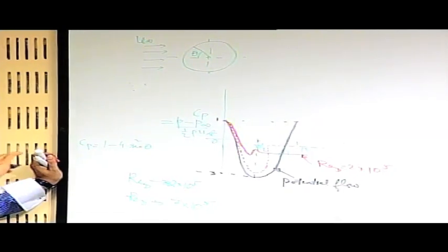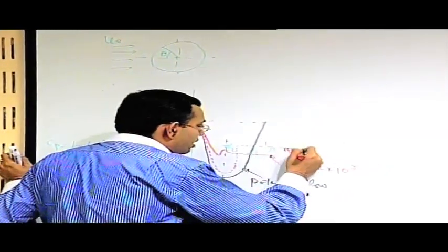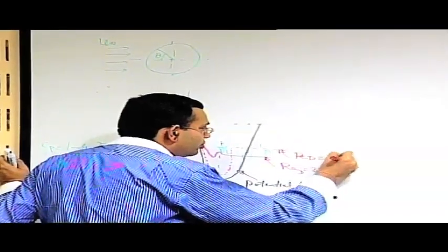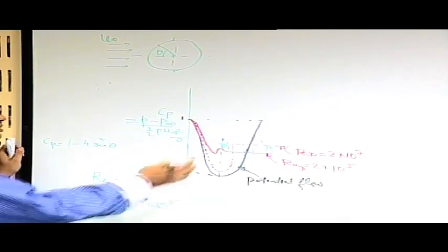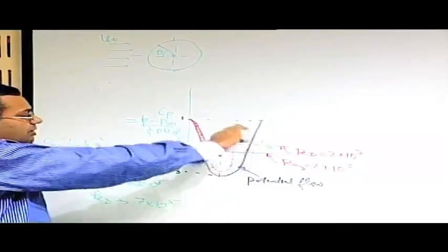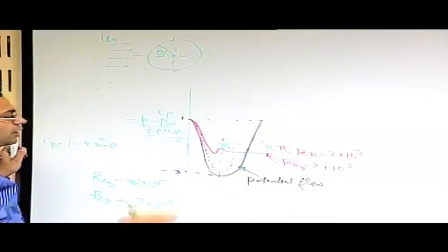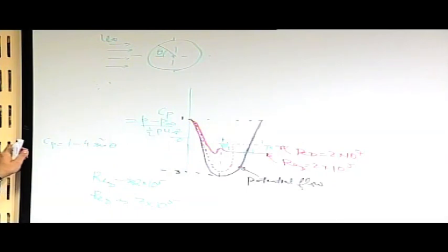That is a constant, the pressure in the wake region is almost like a constant. So this is the higher Reynolds number case, and the angle from which this change of behavior is observed depends on the separation. For laminar, close to 80-82 degree, maybe for turbulent close to 120 degree, something like that.